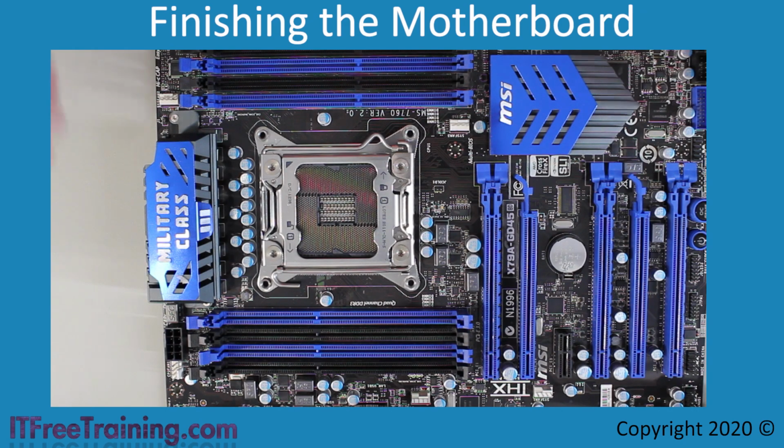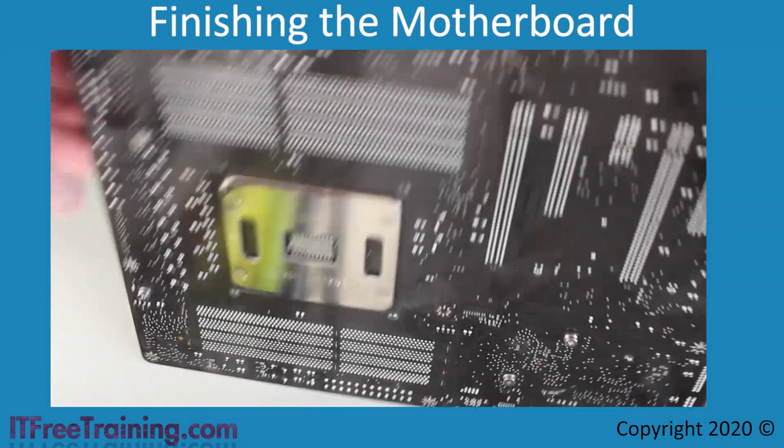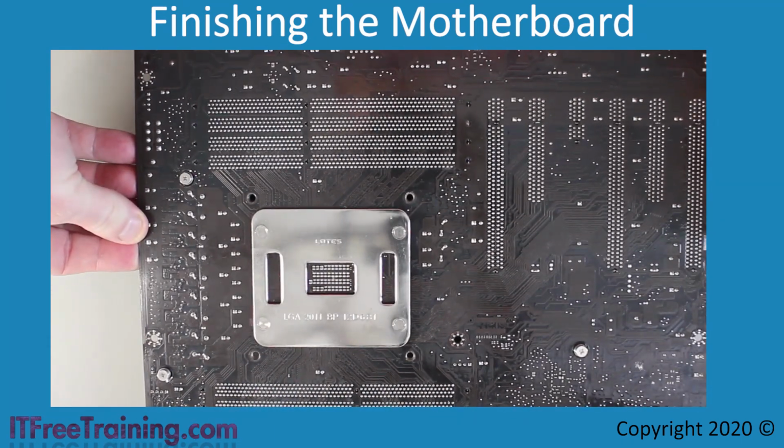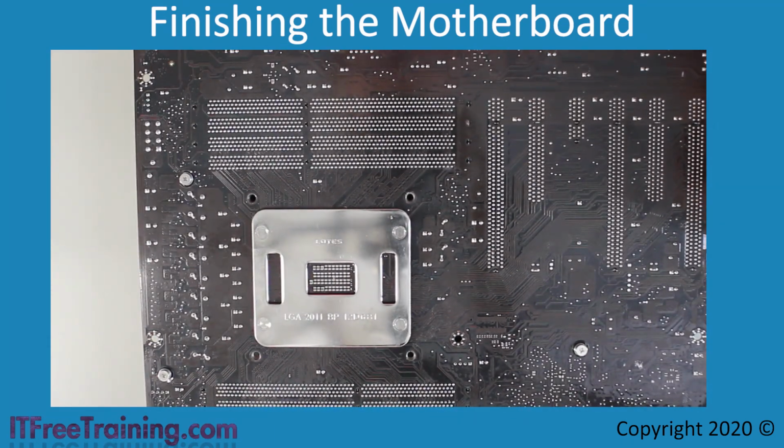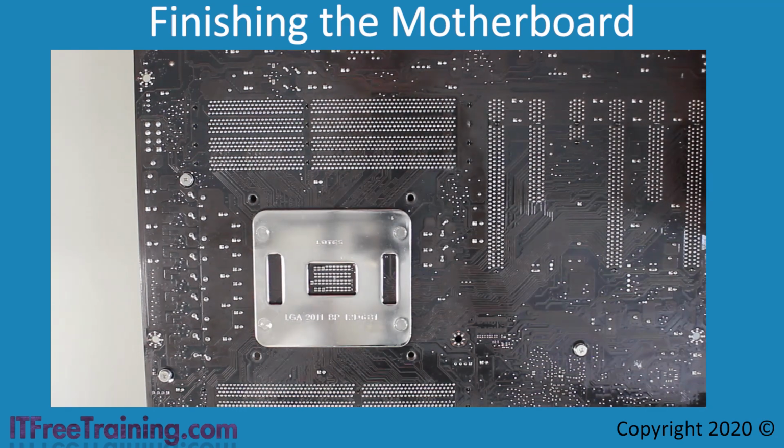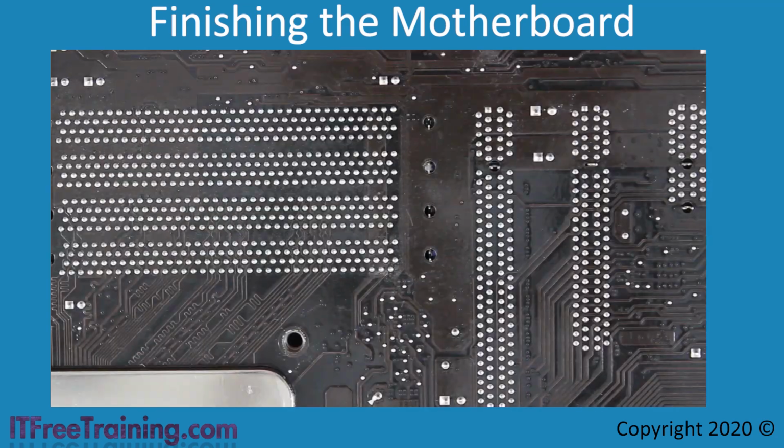I will now turn the motherboard over and have a look at the back of it. On the back of the motherboard, you can see there are a lot of traces. A lot of these traces appear to be going to the PCI Express slot, but having a closer look shows they in fact do not. They essentially go past the pins on the slot, but do not connect to them. Now, if you consider there are very few noticeable traces on the top or bottom of the motherboard going to the PCI Express slot, there must be traces inside the motherboard that connect to the PCI Express slot.